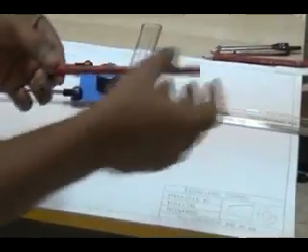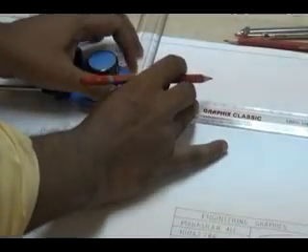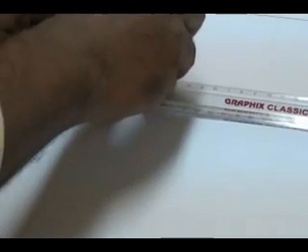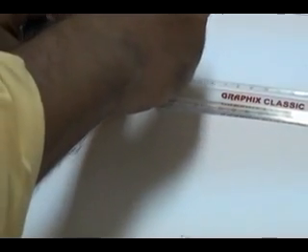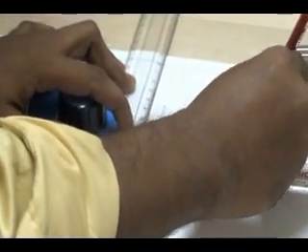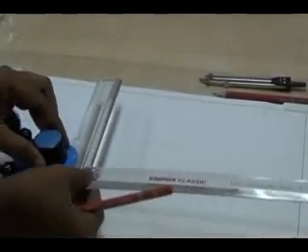Then I am bringing my drafter. I am drawing a horizontal line like this with an H pencil. That is an object line, actually the original line. I am drawing to the length. Then you see, this is the original line. Then I am changing my pencil to 2H. This is all since I am going for a construction, right? So you have to shift your pencil to 2H.